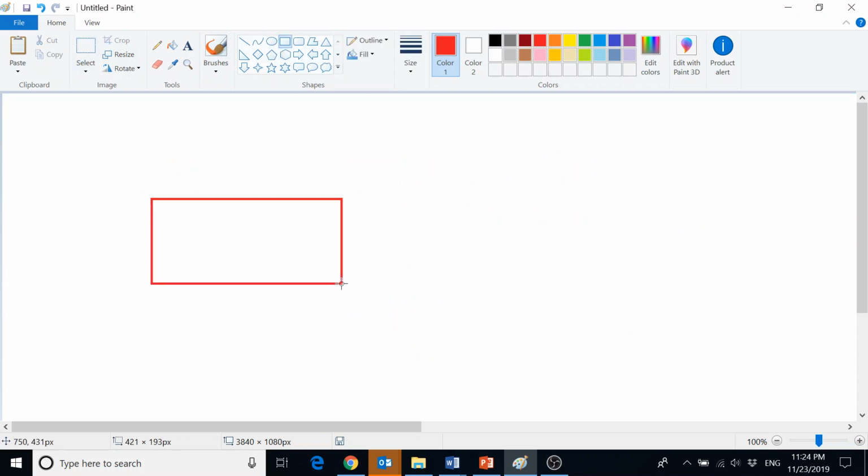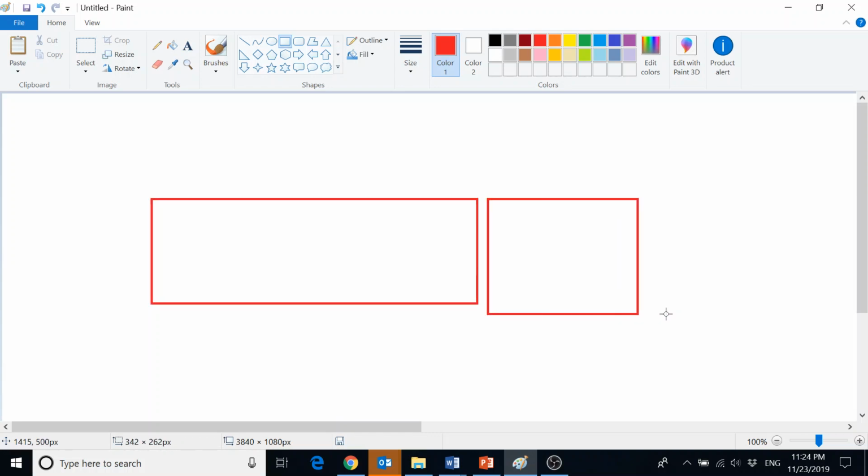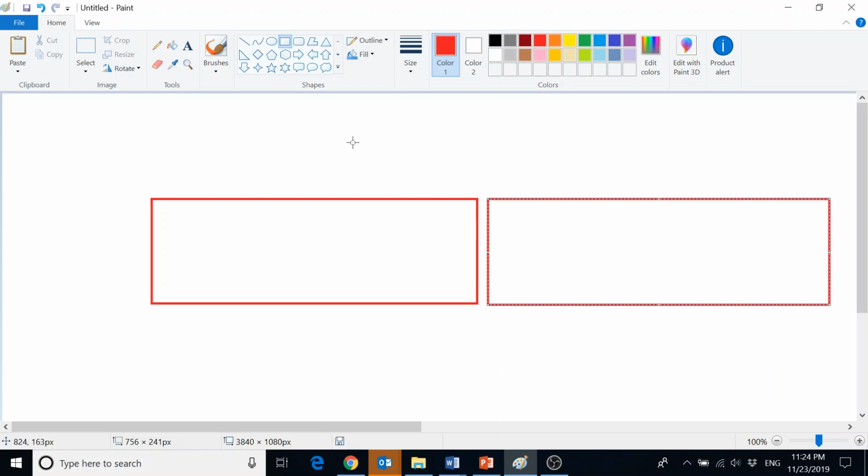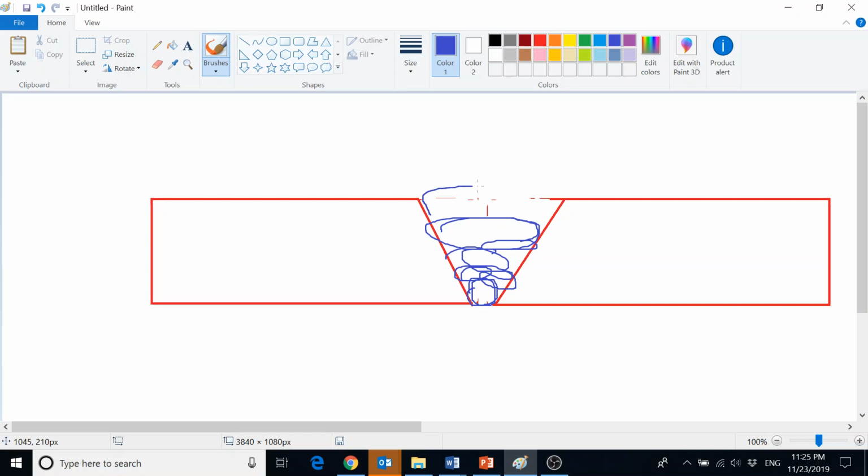For example, you have this piece, I'm exaggerating here, and another piece, and you want to weld them together. So how do you do that? You could do a full penetration weld. Then typically you need to cut it like that, then cut this side like that. Once you cut it, this part is gone, right? Then you have a V-shaped gap where your worker comes in and starts welding. They'll weld the first pass, then the second, the third, the fourth, depending on how thick this is. Maybe a couple of passes will weld it. Then this becomes your welded piece. This is a full penetration weld.